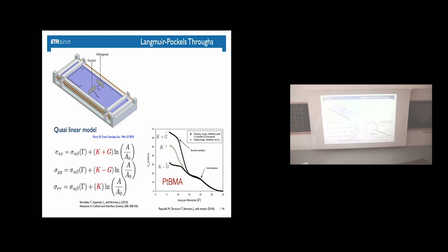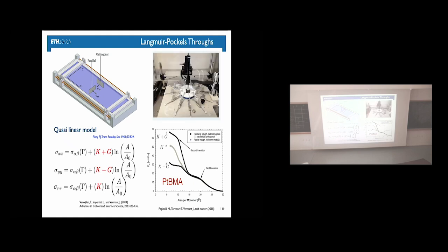So the worst would be materials with a high shear modulus. So networks, gels, 2D interfaces. If I have a low shear modulus, so that depends. And I must say, I don't have that intuition yet on what controls the Poisson coefficient in interfaces. If I have time, I may give you one example where you can even get auxetic materials with negative Poisson coefficients at the interface. So it's fantastic. Anyway, all the misery of mechanics then comes into play, right?